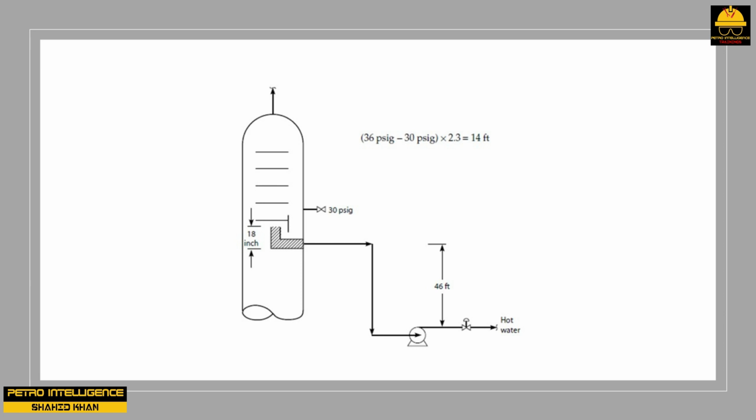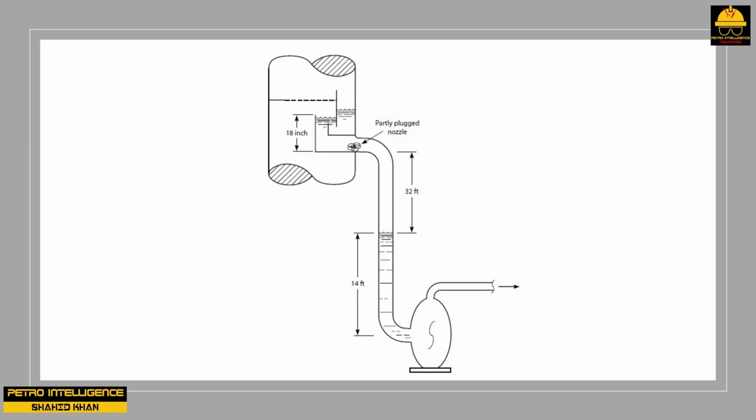But it still seems as if I am missing at least half of the 46 feet of liquid head to the pump. Where is it? Well, dear gentlemen, it no longer exists. Picture illustrates the true situation. Let's say we are pumping 110 GPM from the pump discharge, but only 109 GPM can drain through the draw-off nozzle.